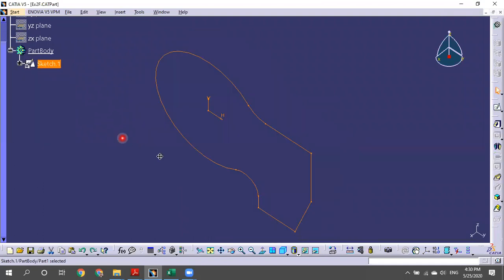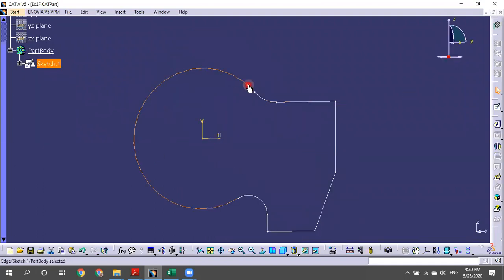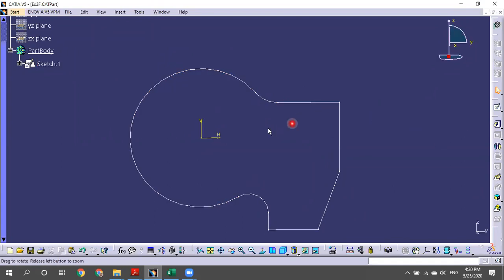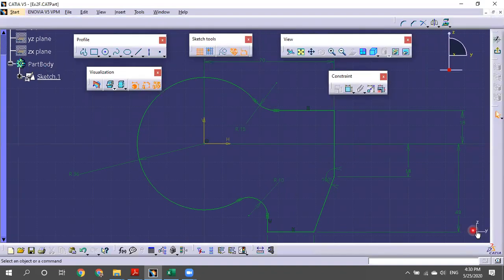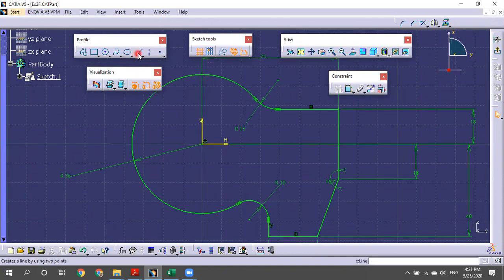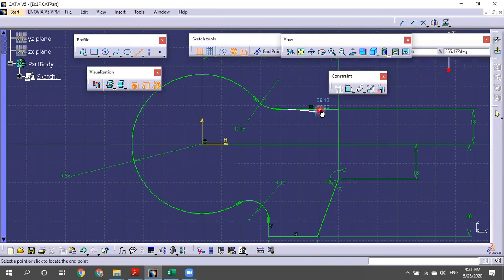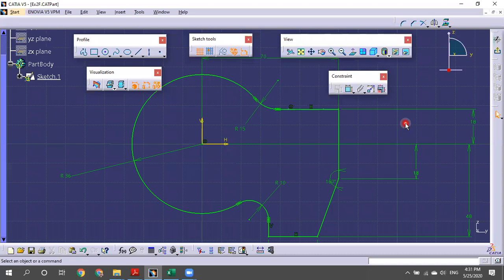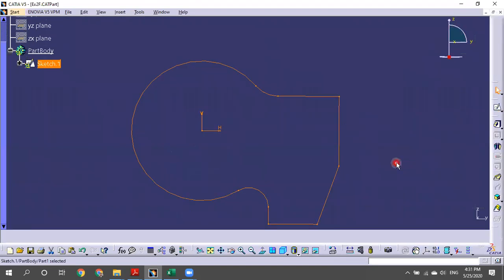So, for example, this is my sketch, right? Double click on it. Just double click on the sketch. Just understand, I'm doing this intentionally. By mistake, I have drawn a line on top of another line. But it still shows green, even without giving a dimension, it shows green. Correct? Now what will you do? I will exit the workbench. See, I will give pad.